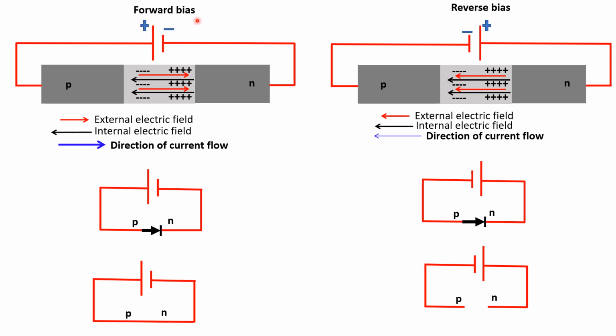In forward bias, we have a very high current, so the junction, the PN junction or the diode, behaves almost as a short circuit, and this current is high because it's a diffusion current, and we have a high concentration of holes in one side, low concentration in the other, and the other way around for electrons.